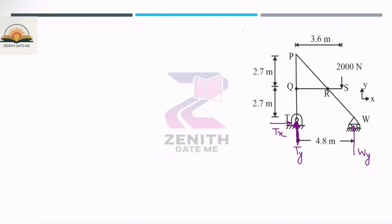So I have represented all these reactions at this point, but please be careful whenever you are applying the reaction, these hatched portions should not be there. Because when you remove the contact, then the reaction will come into the picture. So Tx and Ty are the reactions at this point and Wy is the reaction at the roller support.